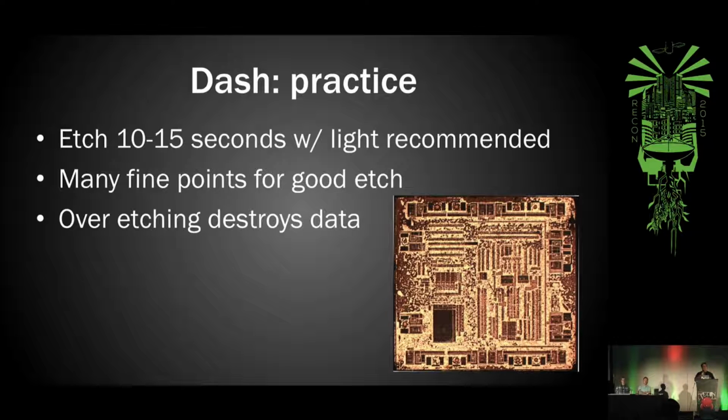So once again, the basic procedure is maybe 10 or 15 minutes of etching. It's actually rather quick. Failure analysis books recommend that you put a strong light on it, like the lights that are blinding me from the audience members. Unfortunately, I haven't really seen much change when I've put a strong light on it, but that's what people recommend.